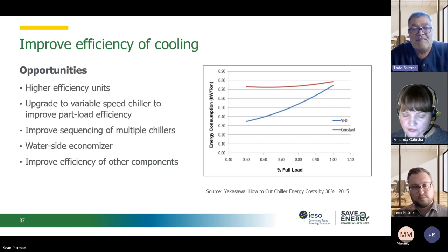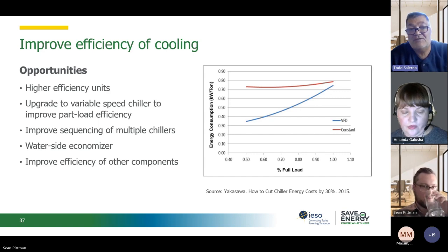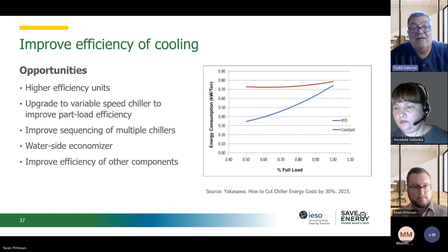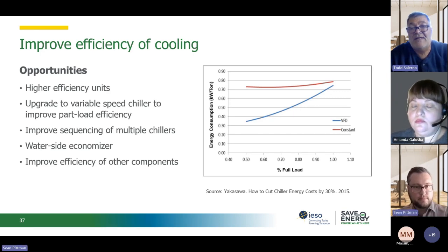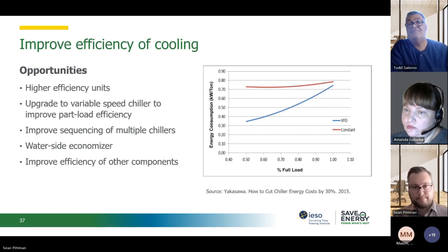Doing the baseline helps you understand how to do the sizing if you are looking at replacing the chiller. You may find that you could go to two smaller units rather than one larger variable speed unit. That might be an option as well. That's why it's really important to do the baseline to figure out how many hours per year you are at that maximum tonnage. Right.